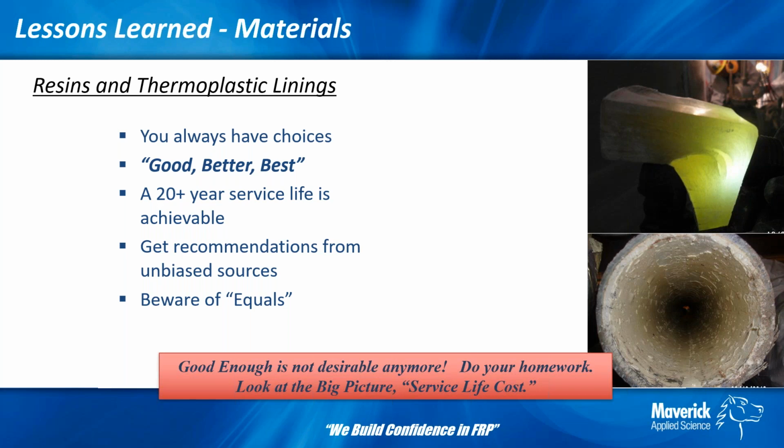I've seen some manufacturers or material suppliers, you'll say, okay, I have this service, these are the design conditions, this is the chemistry, and they'll say, okay, well, it's a dual laminate, and here's the lining. What we find is, if we go to 3 different suppliers, I might get 3 different answers. One will say PVC, one will say polypropylene, another might say PVDF. And what I find is they all will work in that application, but one may be good for 7 years, one may be good for 10 years, and the other may be good for 20 years.